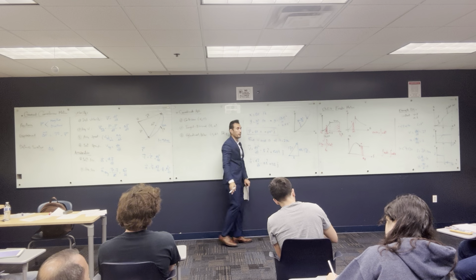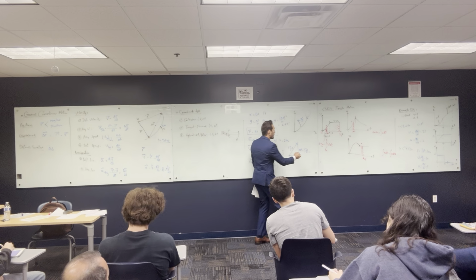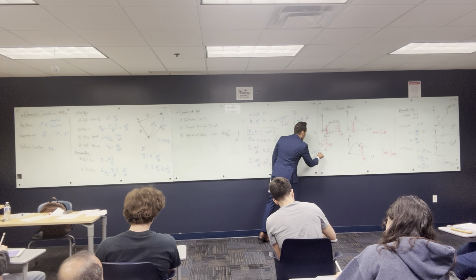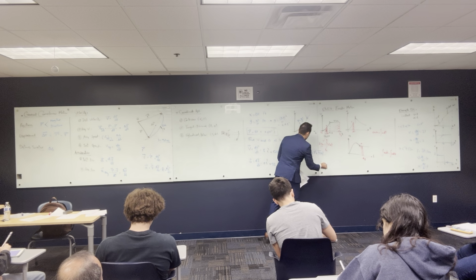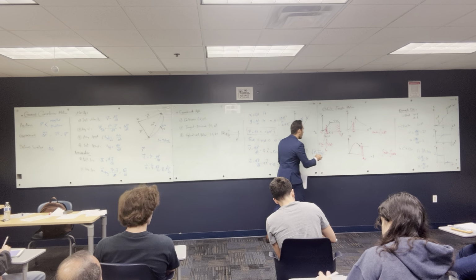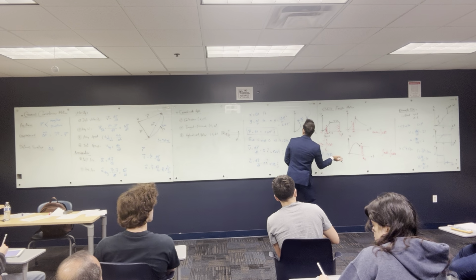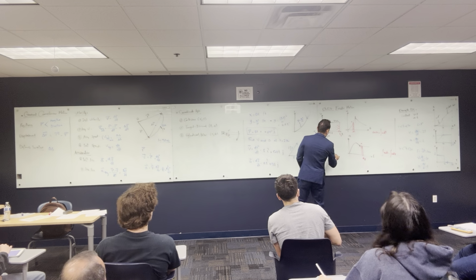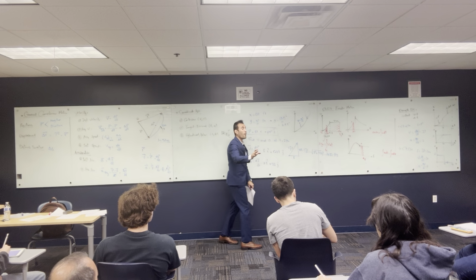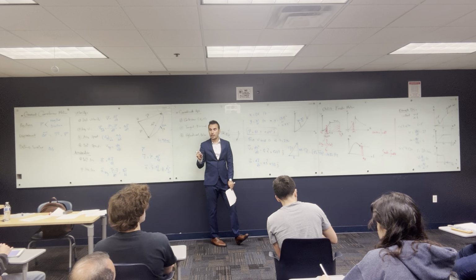The absolute value of v? It's a right triangle, Pythagorean theorem. So you are going to get the square root of 8 squared plus 12.8 squared. And this is going to give you an absolute velocity of 26.82. Is it meters or feet? It's feet per second. This is the velocity. Okay, right now I got the magnitude. How can I get the direction?